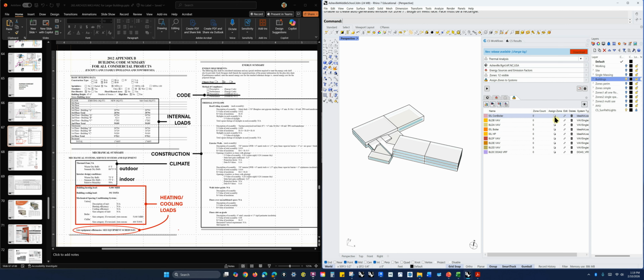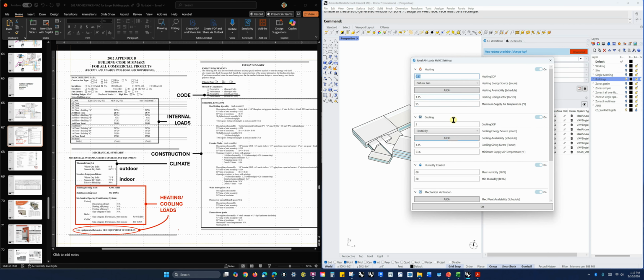Con boiler means I've got a condensing boiler, but you don't see that. All that means is the default typically for this would be 0.8. That's just their default. If you go look at systems for boilers, this is heating COP. We talked about COP. So I'm saying my boiler has a COP of 0.87. I chose that because that's what I found when I went back and looked in the equipment schedules for the project that were specified in the plans.